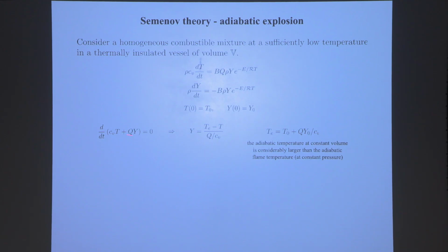And so you can again add the equations to eliminate the reaction term, and you end up with the adiabatic temperature, which is different than the adiabatic temperature that we have been talking about until now, because in a closed vessel, it's not under constant pressure, and adiabatic flame temperature was defined under isobaric conditions.